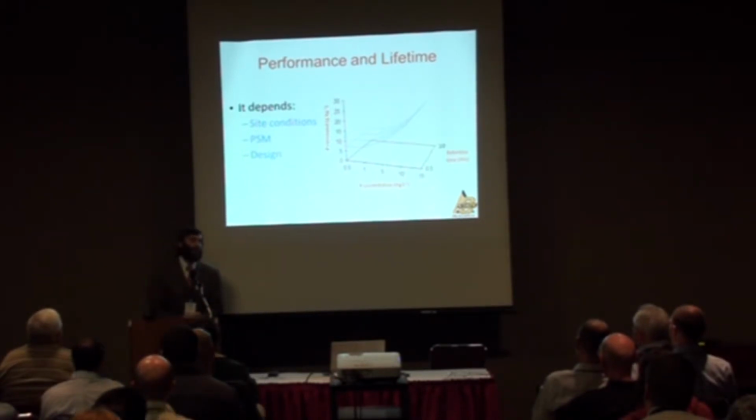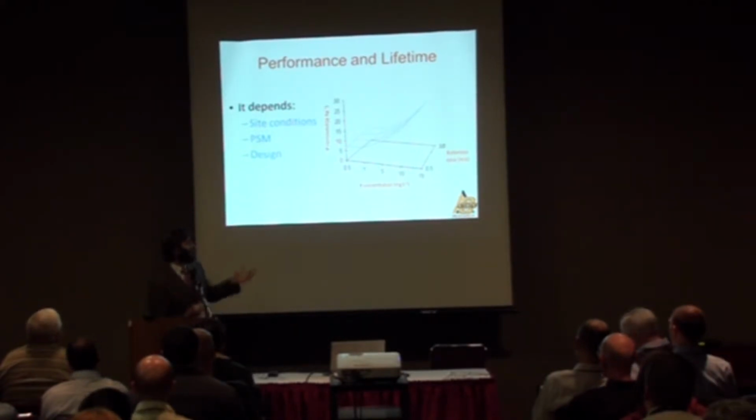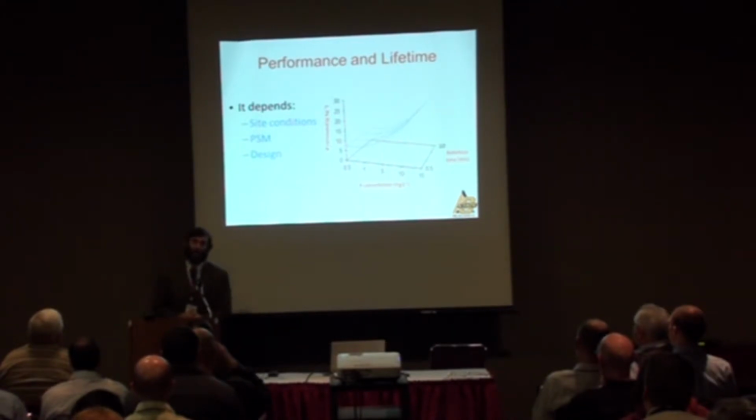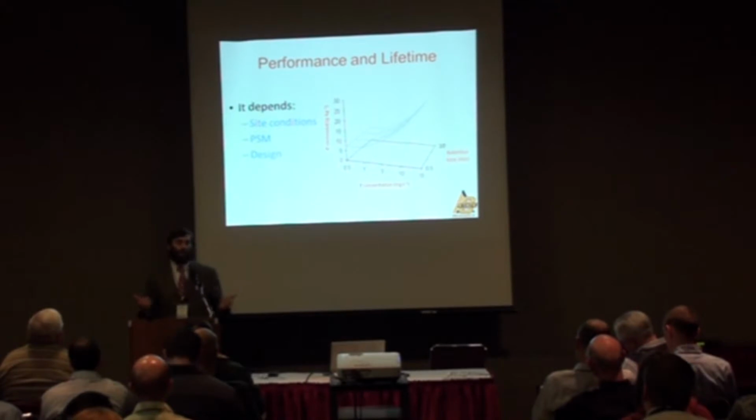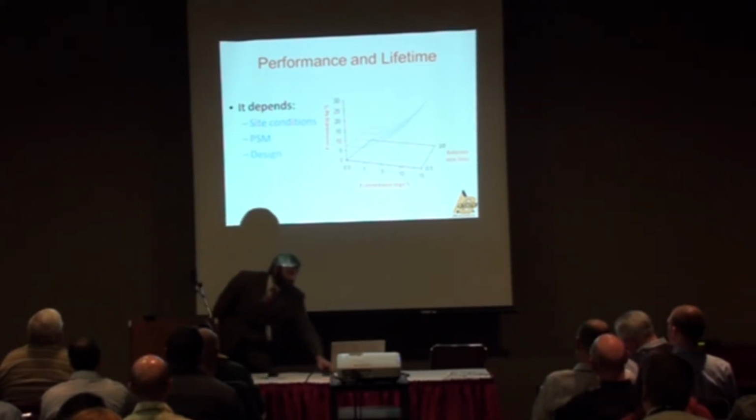Just speaking of the phosphorus sorption materials themselves, the runoff concentration of phosphorus flowing into it makes a big difference. And also, for some materials, they're very sensitive to retention time. In other words, certain materials remove more phosphorus if the water is in contact with them for a longer period of time. Other materials are not very sensitive to retention time.